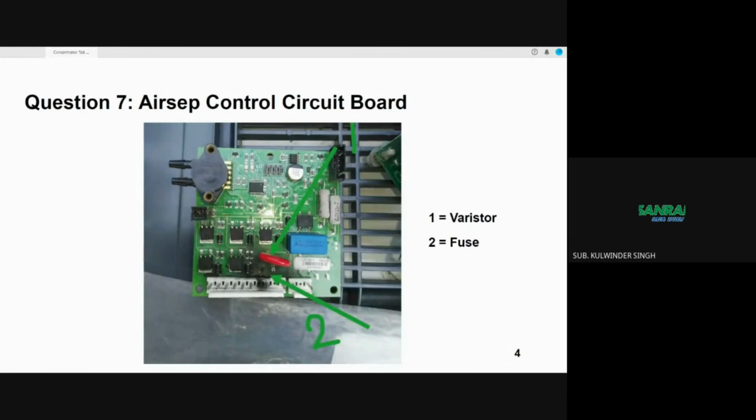So when oxygen concentrators are run without voltage stabilizers with an unstable power supply, the circuit boards are prone to such damage. A voltage stabilizer is an electrical appliance which is designed to deliver a constant voltage to a load at its output terminals regardless of the changes in the input or incoming voltage supply.